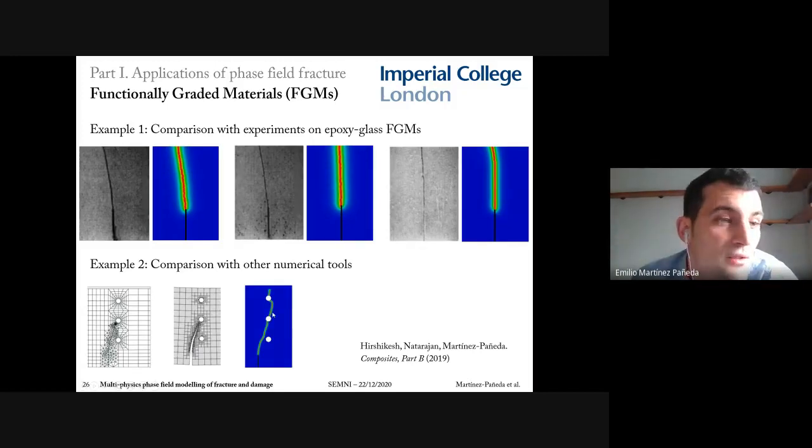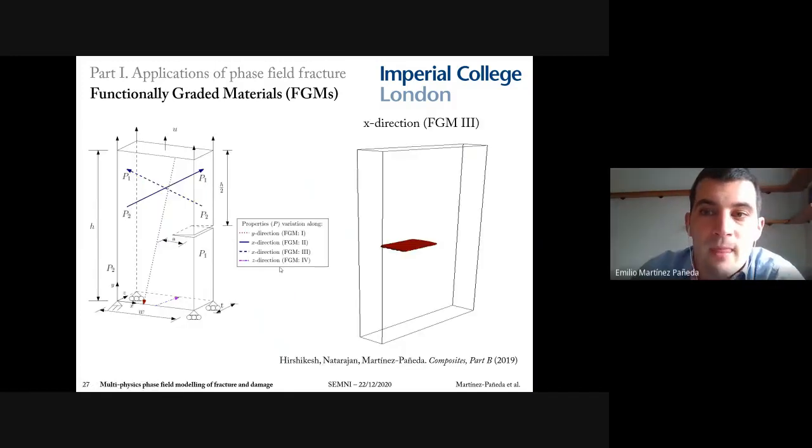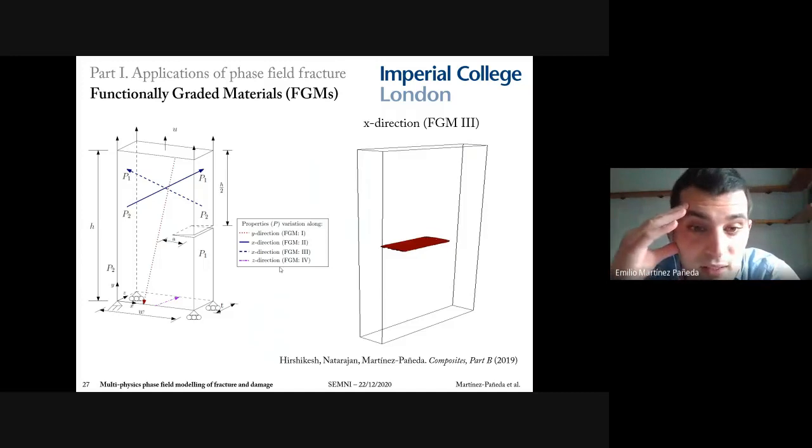The calculation doesn't stop when the crack reaches the hole. You can capture how it will nucleate again, all the way into the complete failure of the sample, and in principle without the need for remeshing. And it can also deal easily with 3D models.